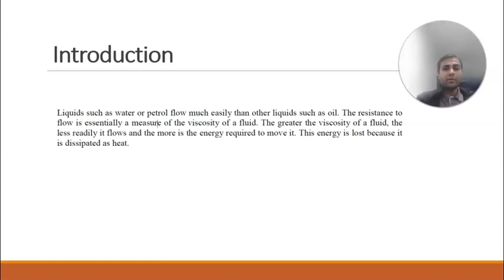Now, if we are looking at energy dissipation in the system, let's say we have a pump, and the pump is pumping a highly viscous solution from point A to point B. The pump has to work extra hard, because as the fluid moves inside the pipe, it causes friction with the surface of the pipe. Because it causes friction with the surface of the pipe, it will generate extra heat. Going back to the first law of thermodynamics, energy cannot be created, it cannot be destroyed. So that heat energy, which is heating the pipe because of the friction of a high viscosity fluid being pumped from point A to point B, is the lost energy which we can avoid.